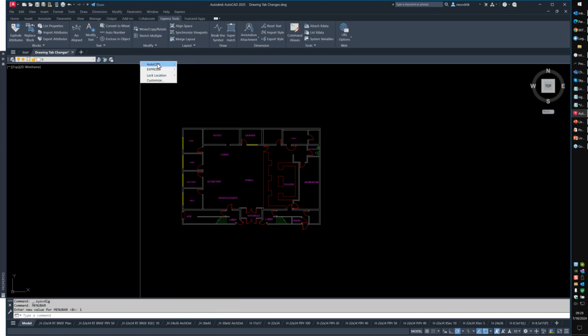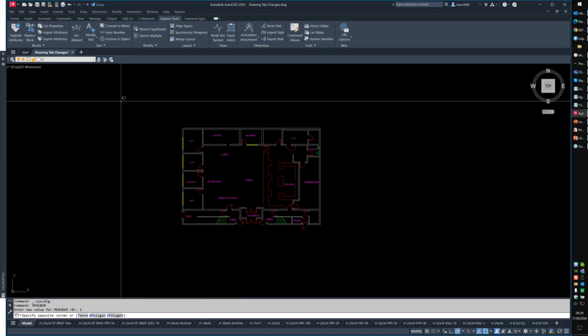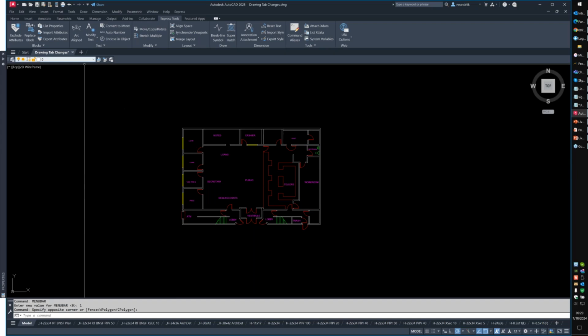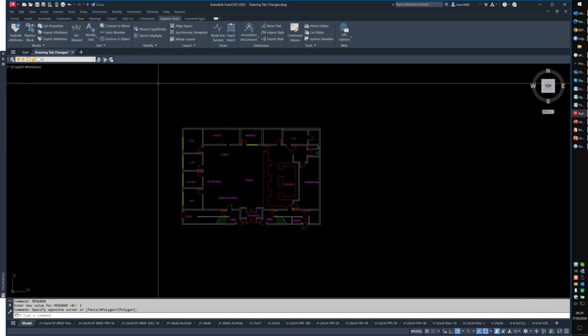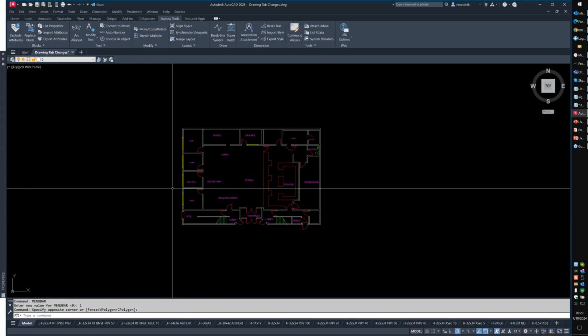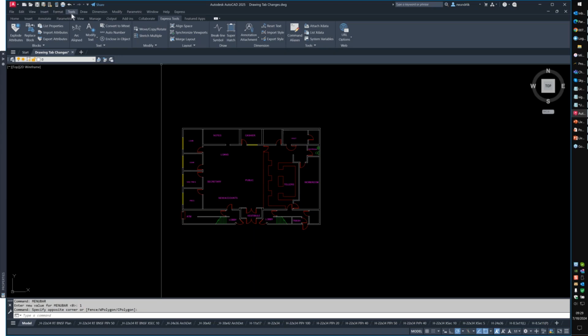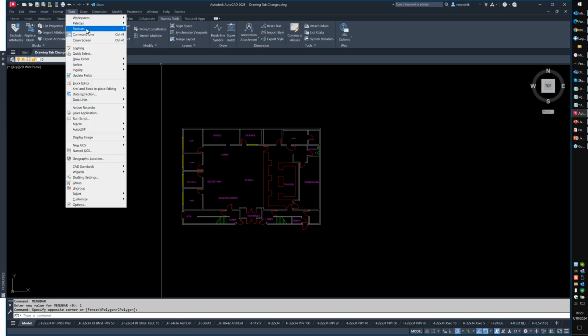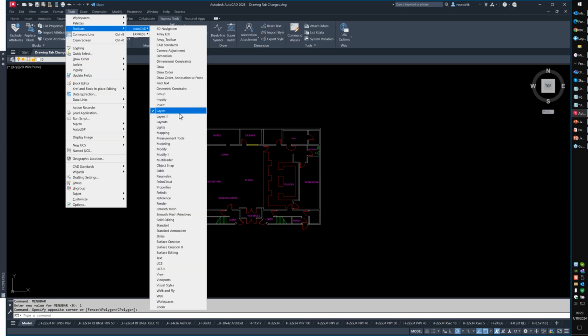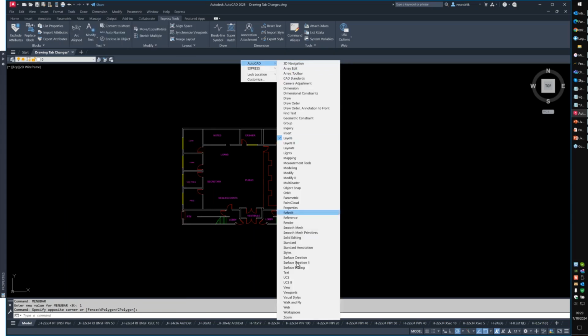So this is typically how I like to do this. One of the first things that I typically like to do when I'm in AutoCAD, this is 25, I have not set up 25 yet, but I have a classic workspace that I bring in that turns off the ribbon, that has just my toolbars, things like that, if I'm doing production style work. So Richard, that's how you do it. Turn on menu bar, come up to Tools, Toolbars, AutoCAD, turn on a single toolbar, whatever you need. Then at that point, you can come in here and you can now do this.